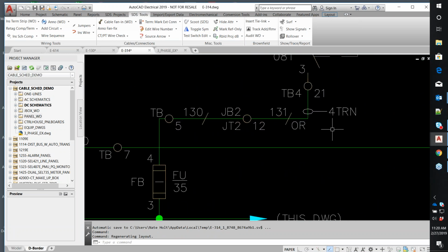So our smart schematics need to show all terminals and all cable connections. That needs to be embedded in the schematic. Now you don't have to actually have them visible. You can put them on a layer that you can turn off if you want. I have all the layers turned on here, so I am seeing my cable markers and all my intermediate terminals. This is a junction box, I think like a marshalling cabinet junction box.